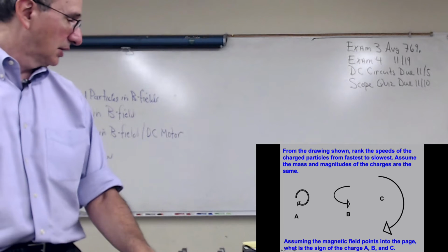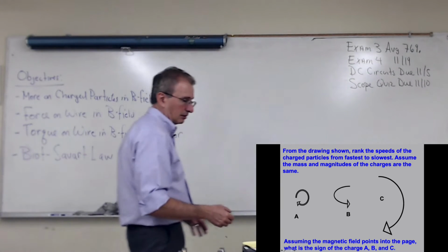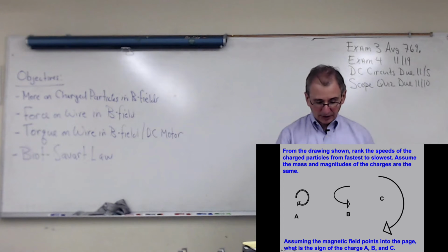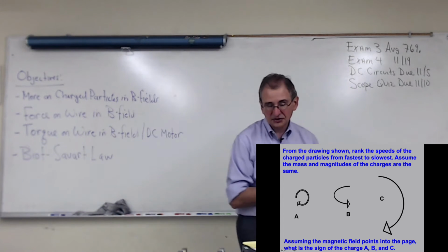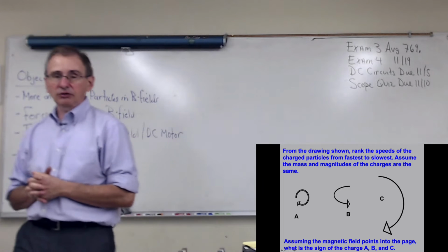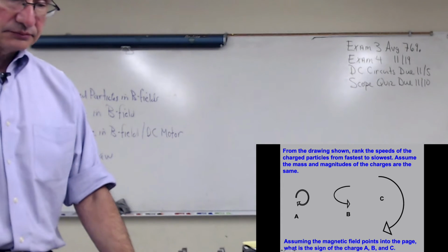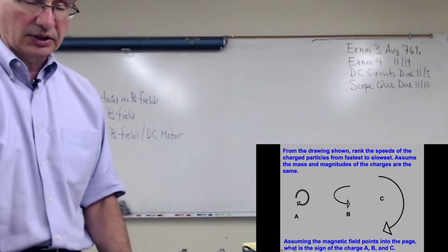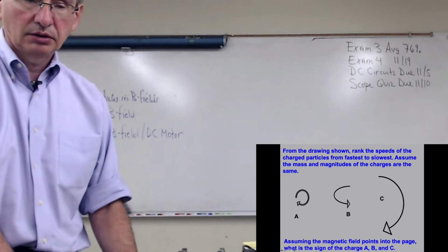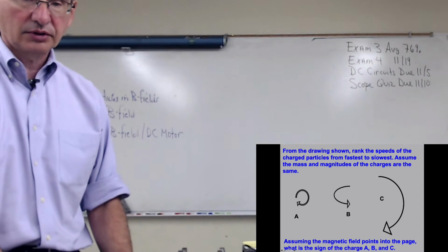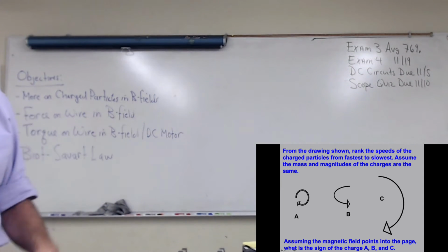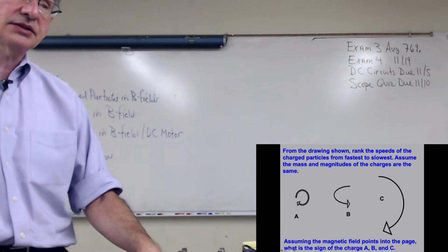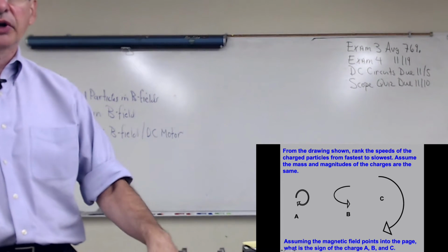We'll have a signal generator, which is a device that we use to generate a time-varying voltage, a signal. You're going to measure the voltage and the period of the signal with this oscilloscope. Basically, you're going to be demonstrating to us that you know how to use it. It's actually not that hard to use. There's a couple little tricky things, but you'll learn those later. We want you to get started on learning this because the subsequent labs are going to require you to use the scope.